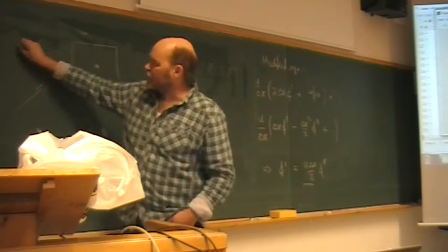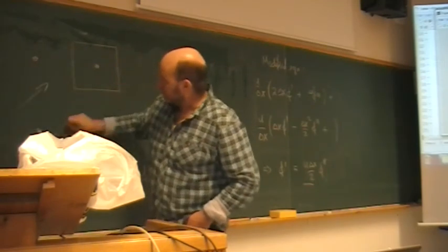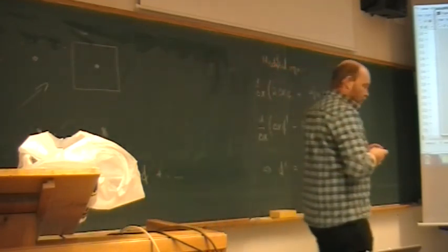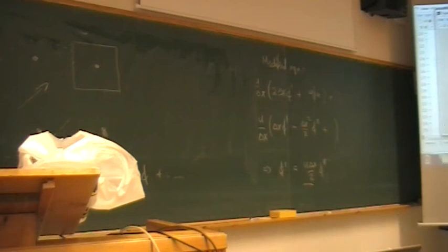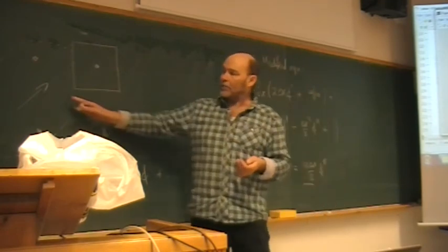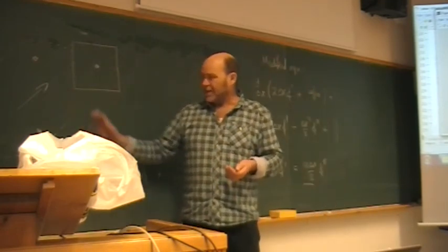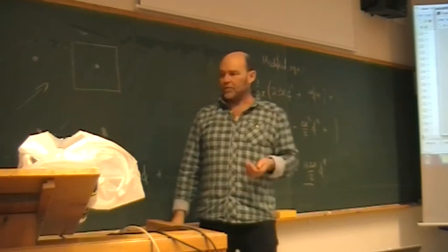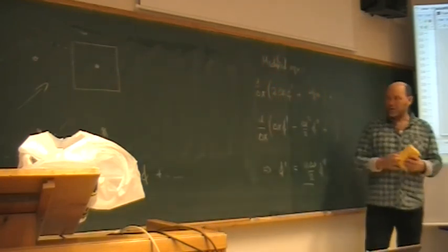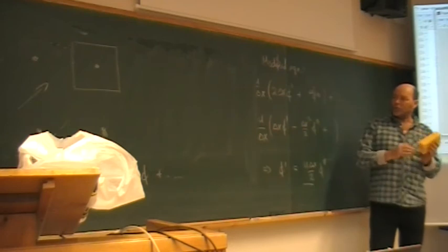Sort of have a region here in this direction, and then interpolating a lot to find out what's actually happening and how it is transported against my cell. So yes, there exist advanced schemes based on such upwind control volume theory, but a lot of geometry, and in the end they are not so efficient anyway.